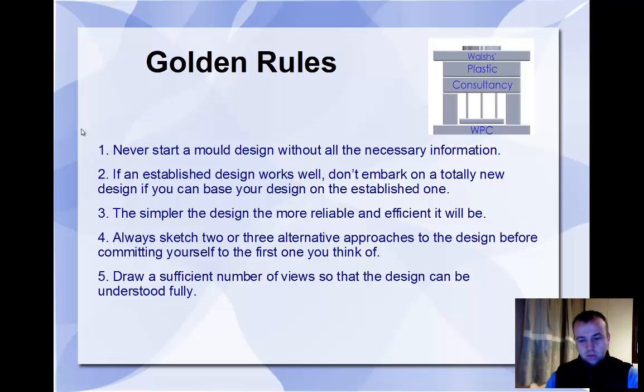Before you commit yourself to one particular design, try to draw out 3 or 4 different alternatives, alternative ways of gating, alternative split lines, etc. Come up with 3 or 4 different options and then choose the best option that meets all the requirements, basically, that can be molded simply and cost effectively.